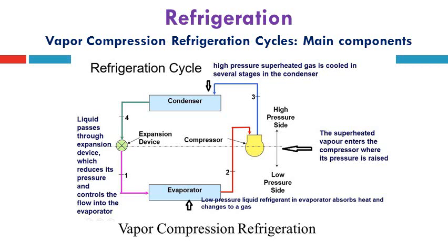After the refrigerant leaves the condenser, its pressure must decrease again to complete its journey inside this refrigeration cycle from state 4 to state 1 when passing across an expansion device such as an expansion valve or capillary tube in small size refrigeration machines.